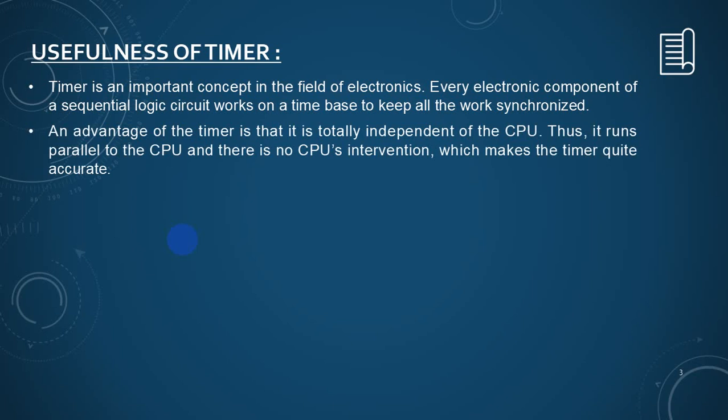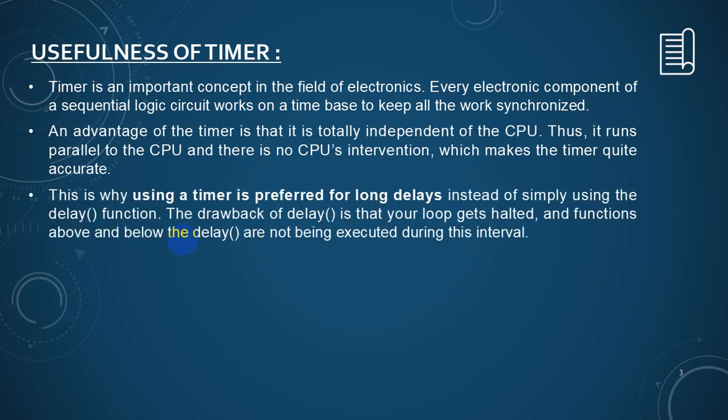Thus, it runs parallel to the CPU and there is no CPU intervention, which makes the timer quite accurate. This is why using a timer is preferred for long delays instead of simply using the delay function, because the timer works independently of the CPU.